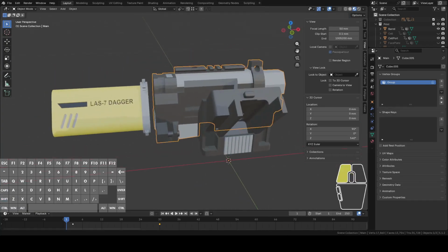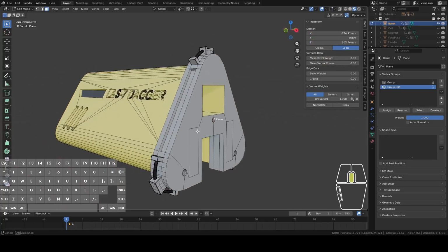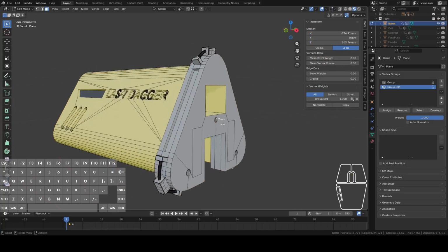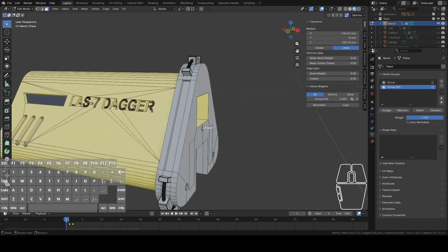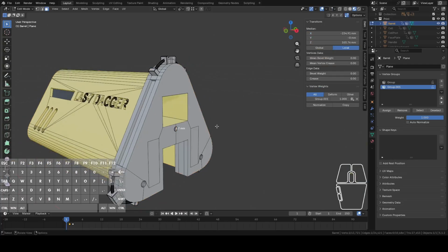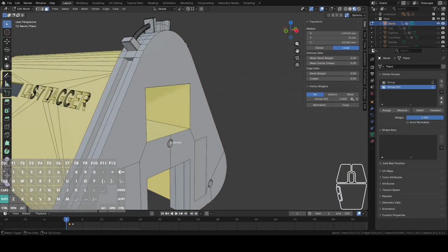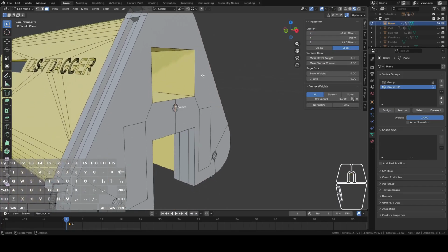Alright, back to printing. A few more issues I recall. First thing is the scale does indeed matter. Even though this is 3.5, 3.7, it's appearing on my slicer as considerably smaller. So to fix that, hit Control A, scale, and now it's reduced based on its size.